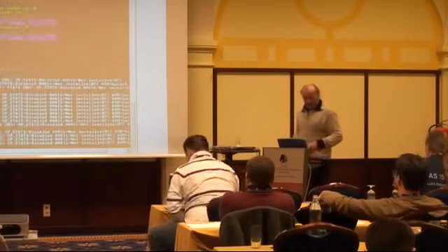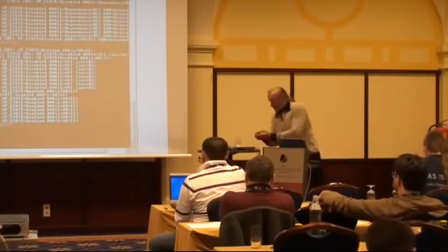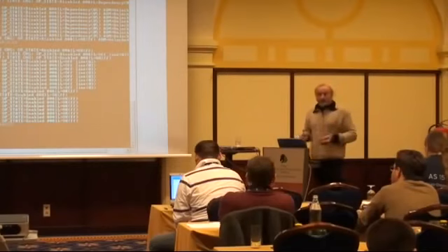So OpenBSC starting up again. Those messages are now the configuration messages when OpenBSC configures the BTS. Now this cell should be visible to the public. So if you do a manual network search with your phone, you should see 00101 or testnet.